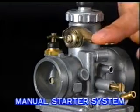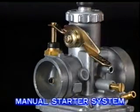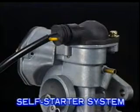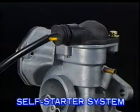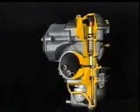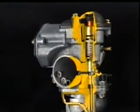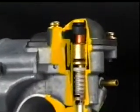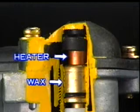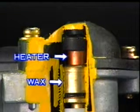In addition to the manual system you see here, where the starter valve is opened and closed by hand, there is also a self-starter system. The self-starter has air and fuel passages just like those in the pilot system. In this system, however, a heating element and wax are provided over the starter valve.